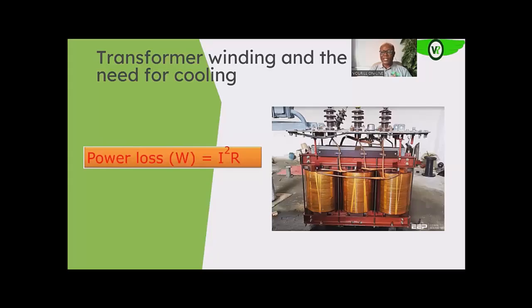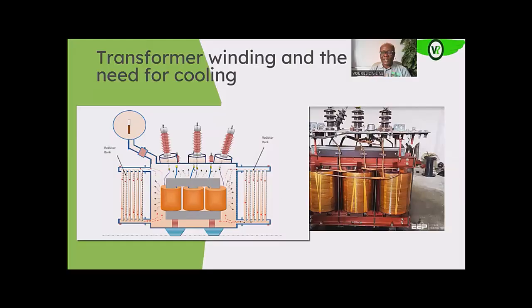So in that case, as we explained earlier when we were explaining the transformer cooling system, the oil removes the heat from the windings. Those oil molecules that are in contact with the windings extract the heat by conduction, and as they get heated up, they move away by natural convection to the tank of the transformer and give all the heat to the tank of the transformer or the body of the cooling fins of the transformer. Okay, so when you look at it, you see that we have natural movement. The oil conducts heat by conduction, and then by convection, the oil molecule moves away. Okay, so that is a natural movement.